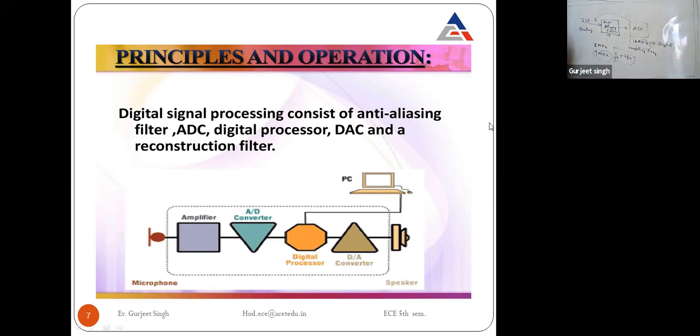Now the fm value is 9 megahertz, so fs is 18 megahertz. But the sampling frequency of our ADC is 16 megahertz, so it will not work on this frequency. Maximum it will work on 8 megahertz, students.